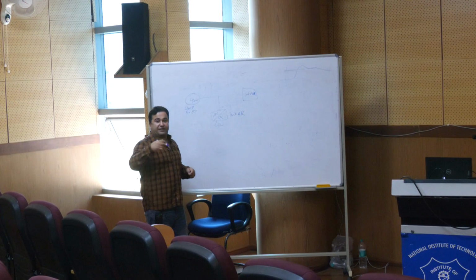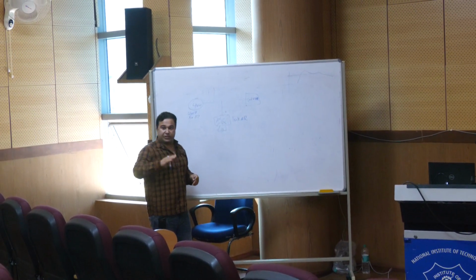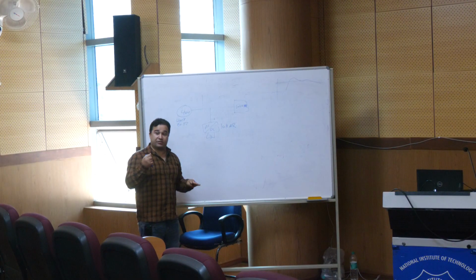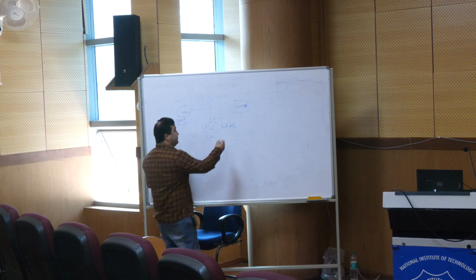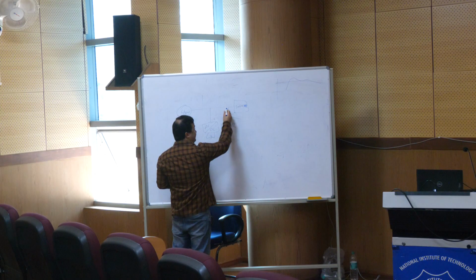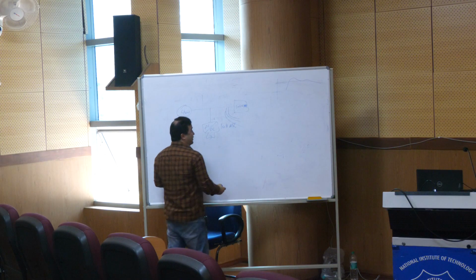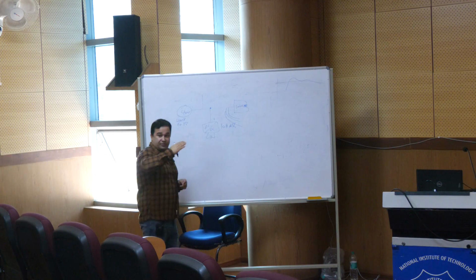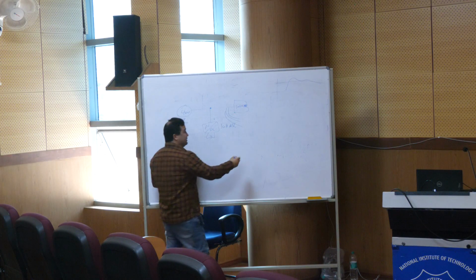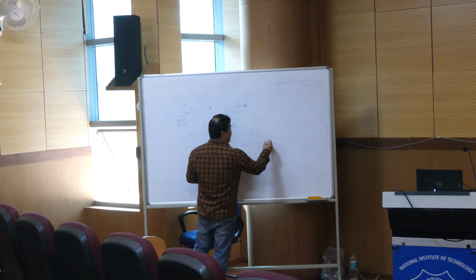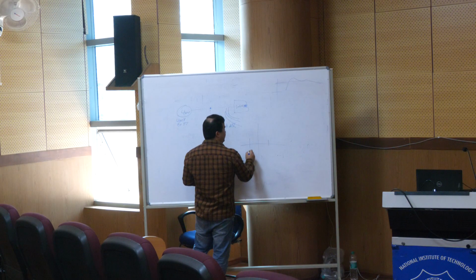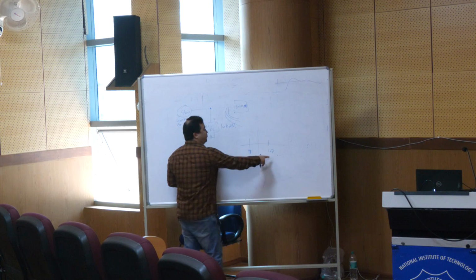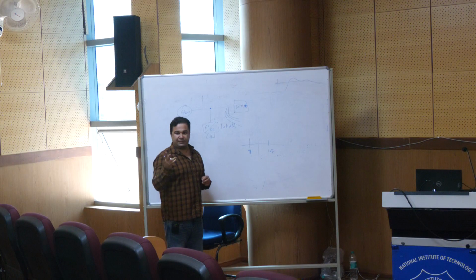When the reactive load increases, the voltage drops. When active power increases, frequency drops. Okay? So when we increase the reactive power more and more, the voltage over the load reduces. If the voltage is between 98 and 102, it means 2%.